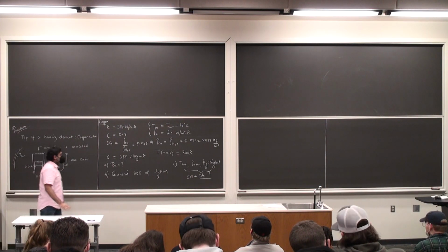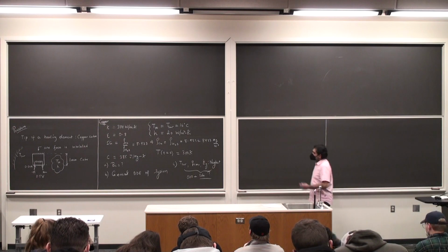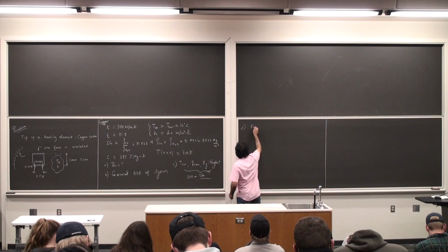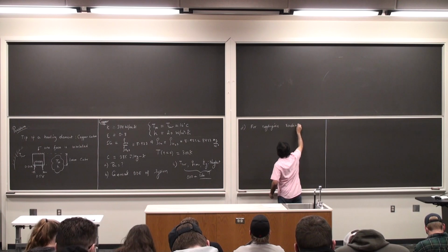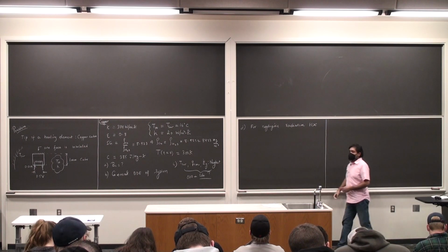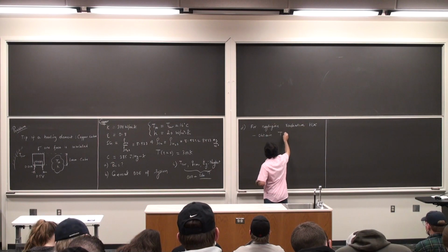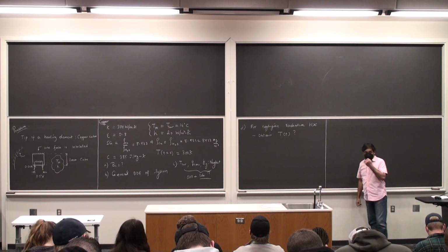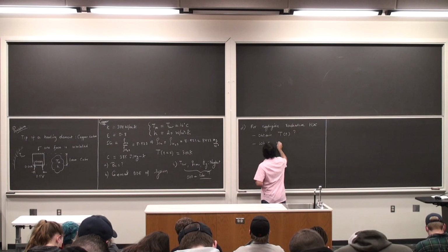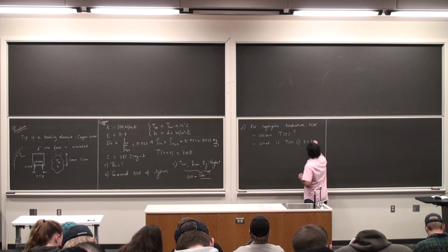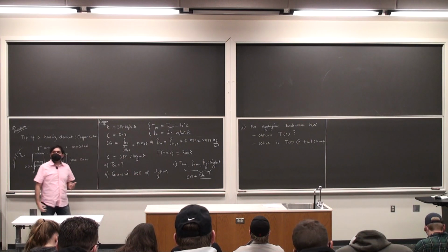And then the last case is the most important one for us, where we make use of convection and energy generation. It's more relevant to our situation. So for negligible radiation heat transfer, obtain the system solution. T as a function of t, and then what is the temperature of the cube after 1.5 seconds? And the Biot number is to establish whether we can assume zero-dimensional conduction.